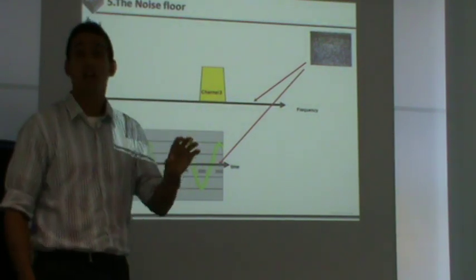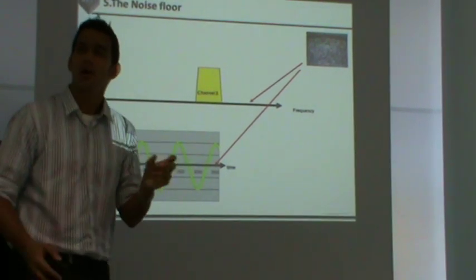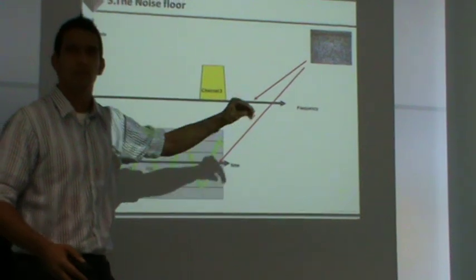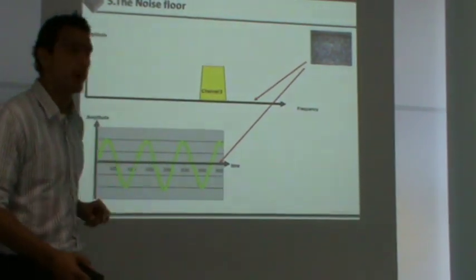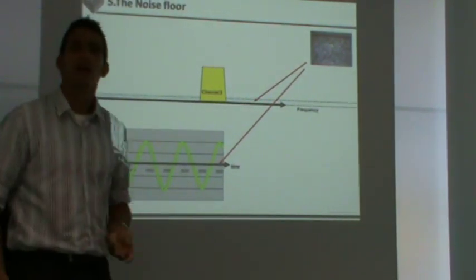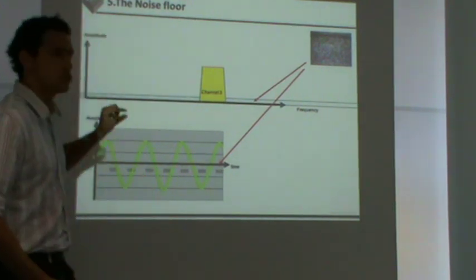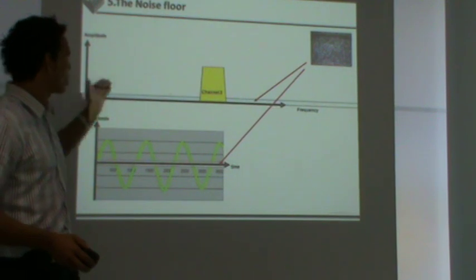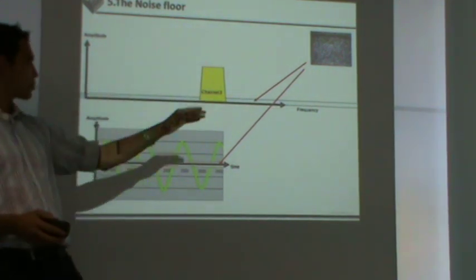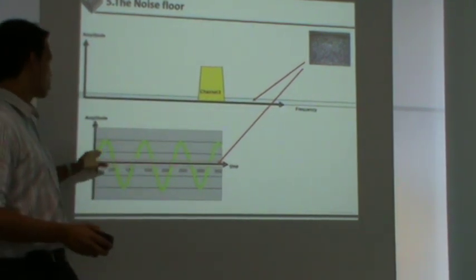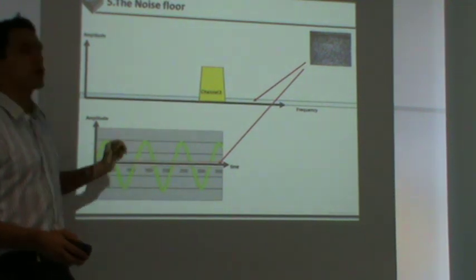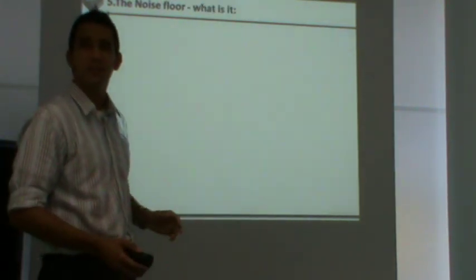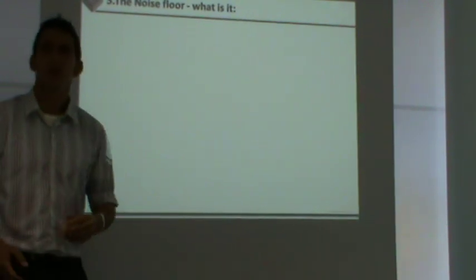So this is what we were seeing earlier on. When you rotate the dial, you actually see this type of stuff. This horrible sort of grey, bubbly sort of thing. What's that? If our noise floor is quite low, if it's a small amount of noise and we've got a nice strong channel, it doesn't matter. So this is looking at our frequency domain, where it goes all the way across. And then here, it's properly tuned, and then we've only got a little bit of noise there. It's okay, our TV can get rid of that. What is the noise floor?